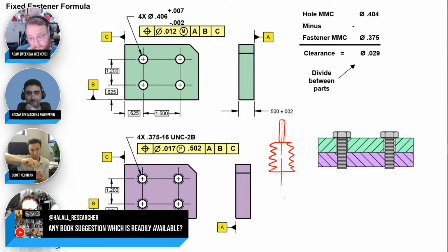But position on threaded holes is hard to measure. Are there any best practices for working with position on threads? Yeah, you probably use thread gauges. So thread gauges are like little things that you can put in there, and then they have like a little stalk or diameter that sticks up, and that would be ground on the center of the pitch. And so then you can thread those into the hole, and now you've got this really nice precision diameter you can touch off of.